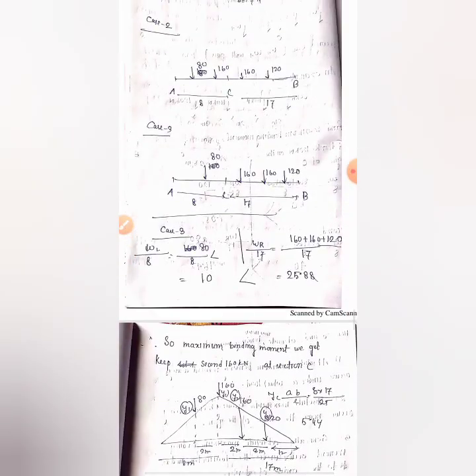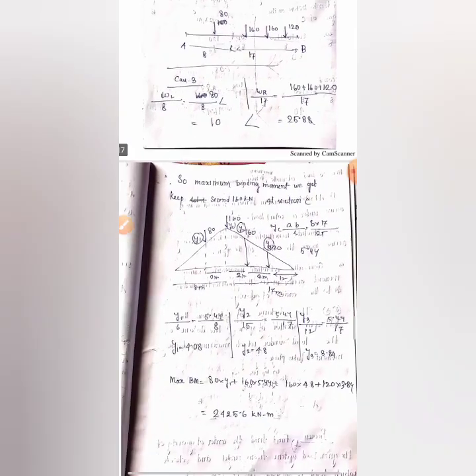Before that condition, in all the above cases, we found WL by A is more than WR by B. But when the second 160 kilonewton passed over section C, we found that WL by A is less than WR by B. That means it is the critical load. This is the load we have to apply over section C so that we get maximum bending moment, right? So I have drawn it, 160